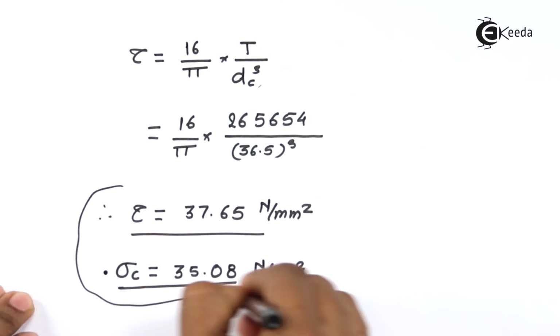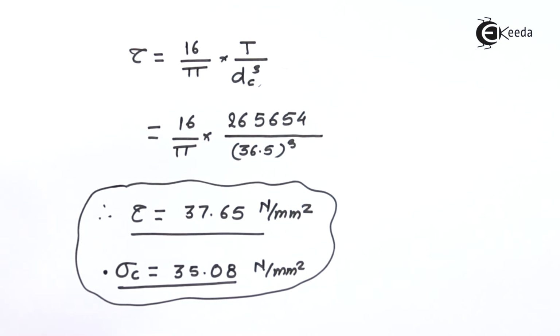Now, one thing that you need to understand, like we had already mentioned in the procedure for power screw design, is that the failure of a power screw is basically controlled by the principal stress theory, where we find out the principal stresses and compare them with the allowable values of stresses, no matter if it is compressive, tensile, buckling, crushing, or shear stress.